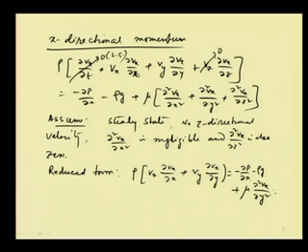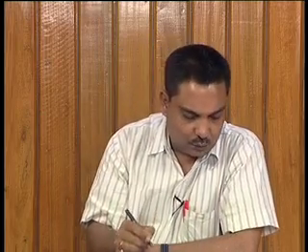Now, what we will understand is that as it is a vertical plate, the pressure gradient would be equal to the gravitational force. So what we will write is that del p by del x, the pressure gradient because of the elevation, is becoming equal to minus rho infinity into g. Rho infinity is the density of the fluid when the temperature is at T infinity, so rho infinity is equal to rho at T equal to T infinity.